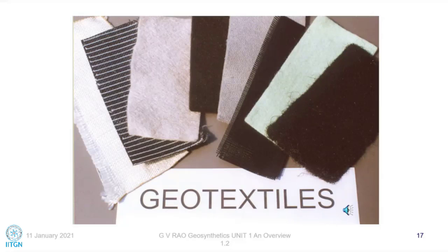So another thing you have to do is that in cases when the geosynthetic is exposed for a limited period to sunrays, it is required to be black in color. Why black in color? We expect that it will have this 2 to 2.5% carbon black. The carbon black has to be in a very fine form. It has to be uniformly, or homogeneously, distributed throughout the geotextile. It's not like a mixture wherein odd things are there. It should not have a black dye. It should have carbon black well dispersed into the material. In fact, when we are making the codes, we are specifically mentioning, Mohan, you remember this term we used also. Dispersion is very important for us, and percentage is important for us, depending on exposure.